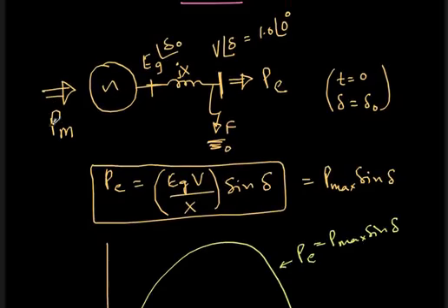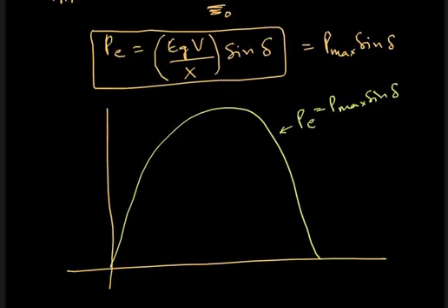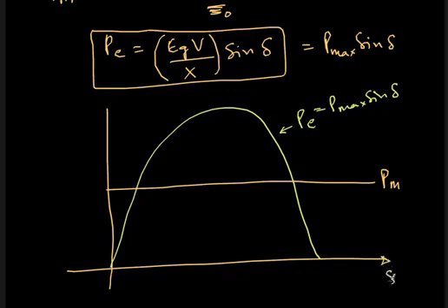It's all under our control, because this is an infinite bus, and I'm just generating power and injecting into the bus. So depending on your prime mover, for example, if it is a steam turbine, depending on the amount of steam, the amount of PM will be defined. So let's say this line represents your PM, and this x-axis is delta, and the y-axis is the power being generated.